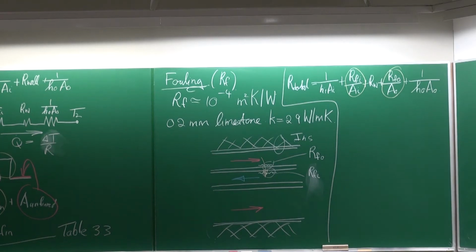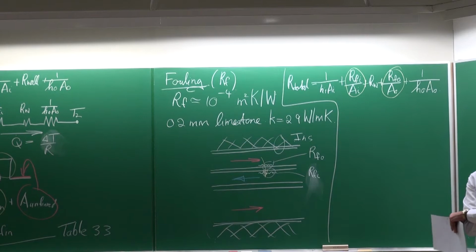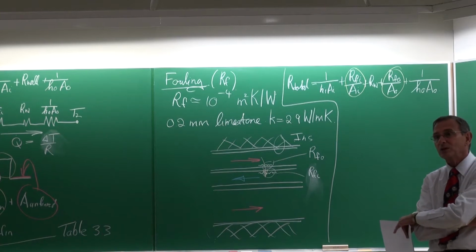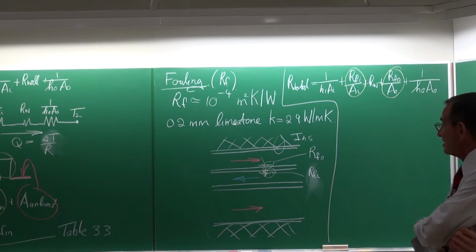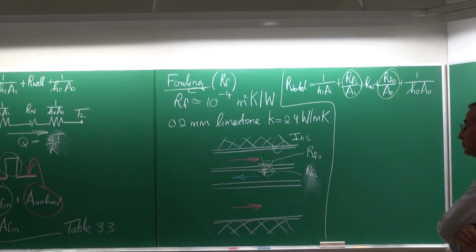Now in industry it is not so easy to know what that value is going to be. Of course, if you've got a heat exchanger in operation, you can go and measure it after 10 years or so. But the problem is, let's suppose it is water, that doesn't mean that for the next year you're going to get the same thing, because water quality can actually vary quite a lot from day to day. So it is a very difficult thing to determine or estimate beforehand.